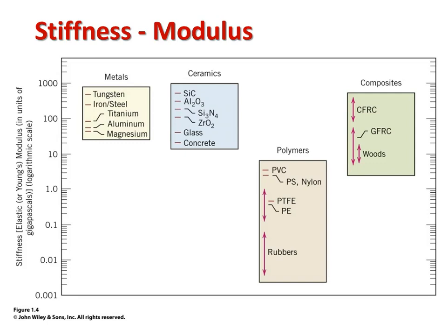We'll definitely be talking about this very specifically in Chapter 7. This is a major design criteria for things that can only move so much given a known loading or vice versa. And you can see from this that there's a good reason to put up with the high density of metals, because for the most part they are all very, very stiff or high modulus materials. Even your lowest density metal, magnesium, still has a fairly high stiffness. So you don't pay much in stiffness to go to a lower density metal. They're fairly tightly clustered and they're all at the high end.